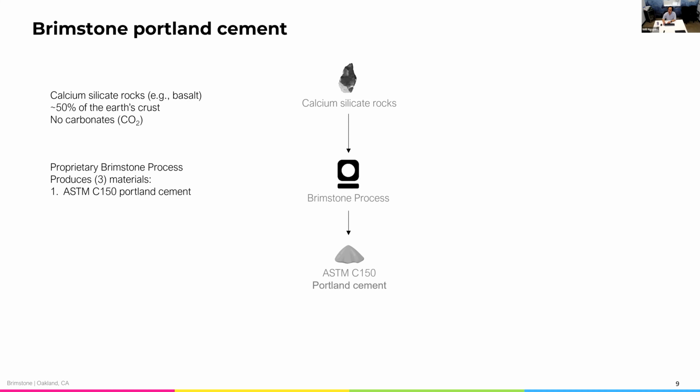I won't go too much into cement chemistry, but our cement does rely on the same cement chemistry as conventional cement. It still has gypsum to control something called C3A in the cement, and it's ground and milled the same way as conventional cement. And so its particle size distribution will be similar or the same as you would find in normal cement, same physical properties.